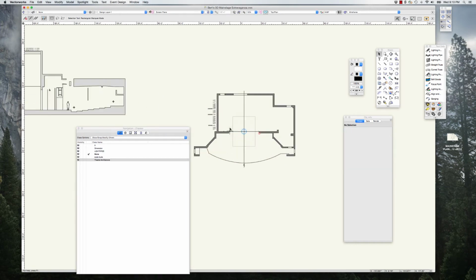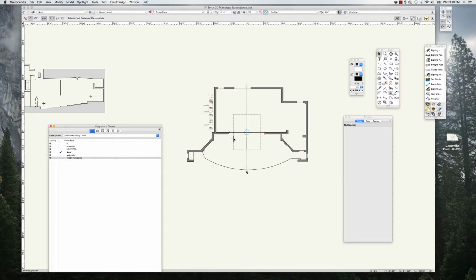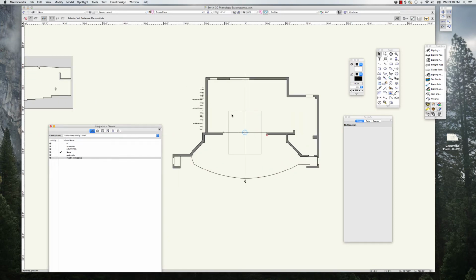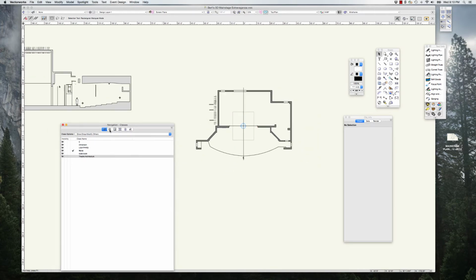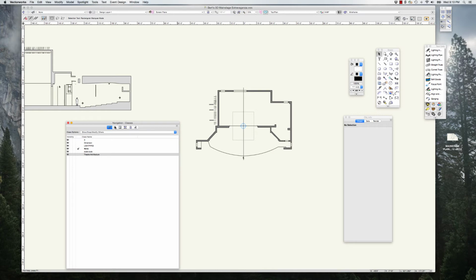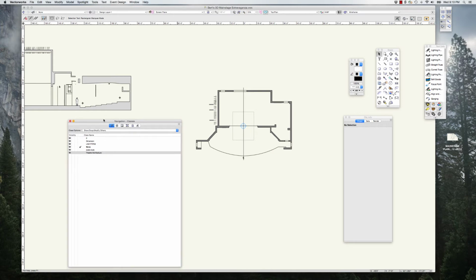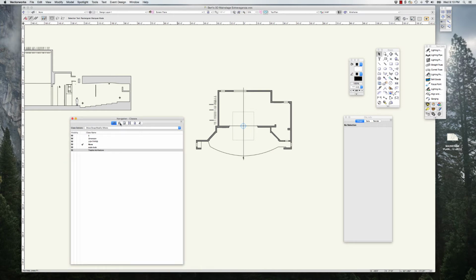because when I create a ground plan for this set that we're putting in here, I'm likely not going to want to have all the lights in the ground plan. I'm going to want to turn them off, and the easiest way to do that is just to put them on a layer and set the layer visibility to 0. By the same token, I probably want to create a scenery layer so that if I were drawing a light plot, I might want to just be able to turn the scenery off. It's easier to do that with a layer than a class.